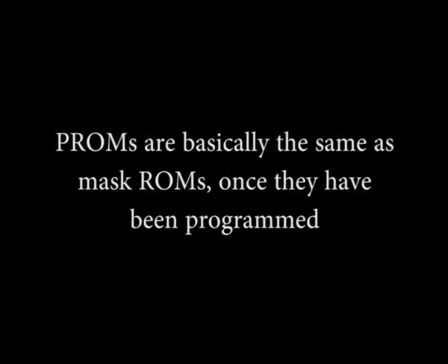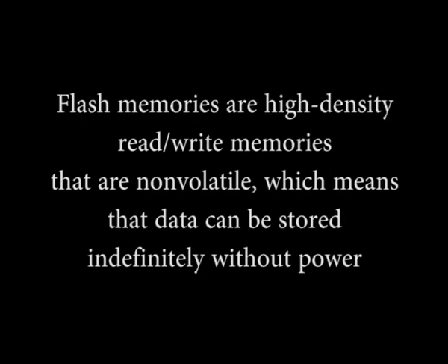So friends, that brings us to the end of our discussion in this lecture, and therefore we sum up. In this lecture, we learnt about ROM family and its organization. PROMs are basically the same as mask ROMs once they have been programmed. An EPROM is an erasable PROM. And finally, flash memories are high density read write memories that are non-volatile, which means that data can be stored indefinitely without power.